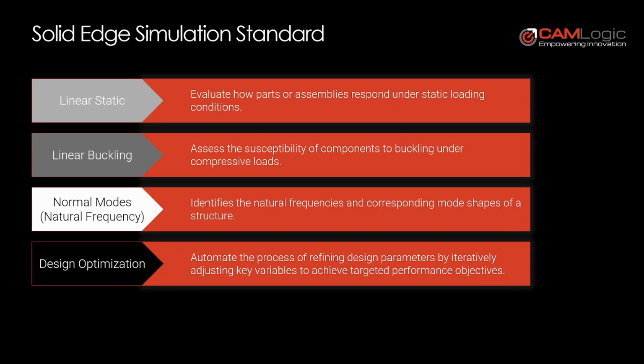So Solid Edge Simulation Standard offers linear static studies, which evaluate how a part or an assembly can respond under static loading conditions. It can also do linear buckling, which looks at how susceptible a component is to buckling when under compressive loads, typically used with longer, skinnier, thinner components, like beams and railings.